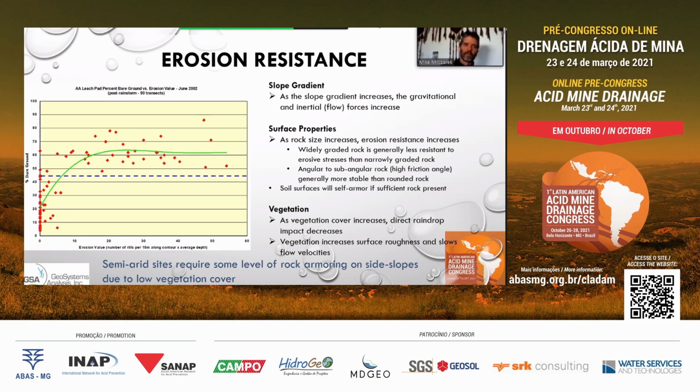And so you want to make sure that you get this level, or if you're not able to get enough vegetation, you need some level of rock armor on side slopes.